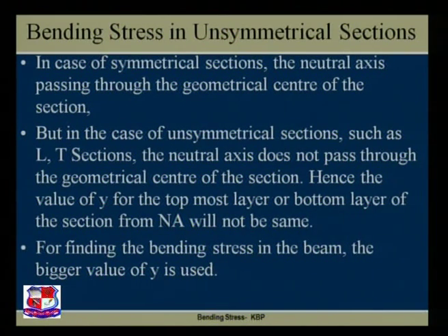Now, let us go to the next type of problem, for the unsymmetrical sections. In the case of symmetrical sections, the neutral axis passes through the geometrical center of the section. But in the case of unsymmetrical sections like L, T, unsymmetrical I sections, the neutral axis does not pass through the geometrical center of the section.